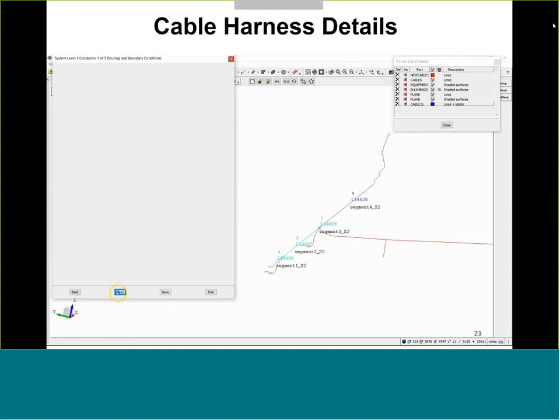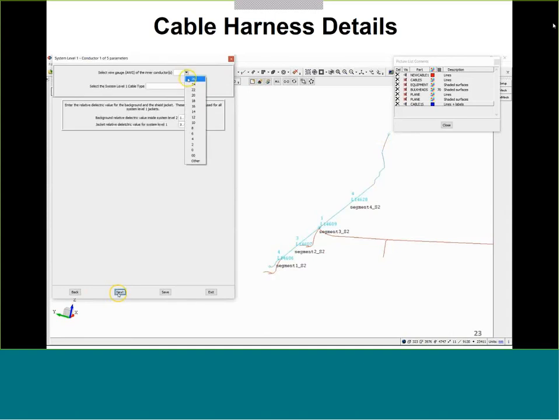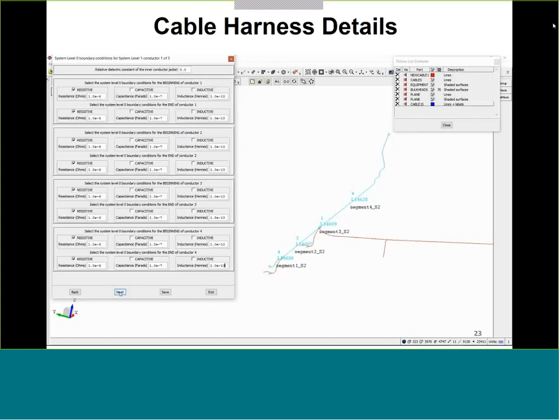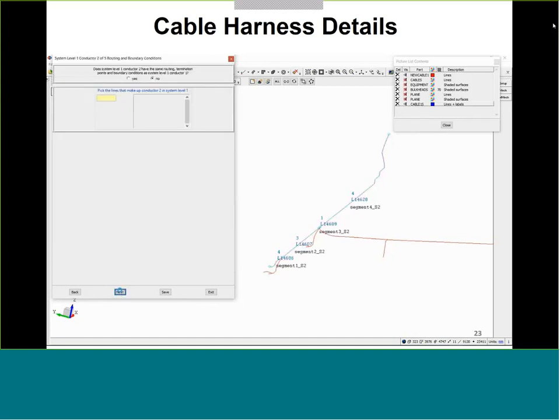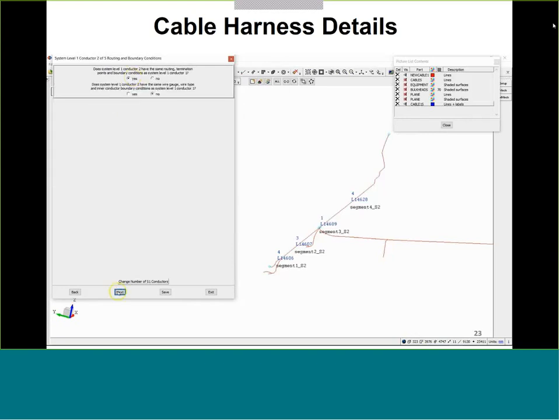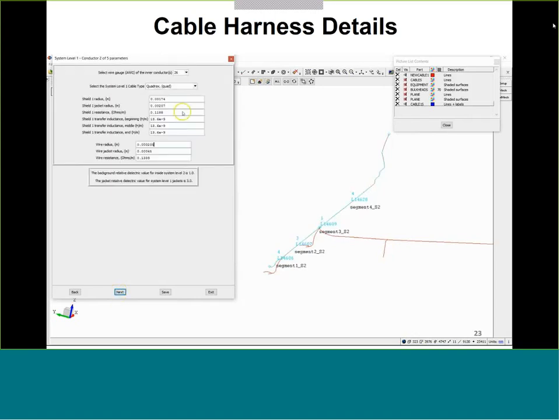And so here's the great part. You don't have to do this work. We have measured tons of cables to understand their transfer impedance. So we've got quads, triples, pairs, singles, coax. We've got lots of gauges. We've measured Glenair cables to get their transfer impedance, and we've also measured Alpha brand overbraid to get its transfer impedance. So this could be a measurement program that could take you weeks to do, assuming you're using kind of typical cables. You don't have to do any of it.